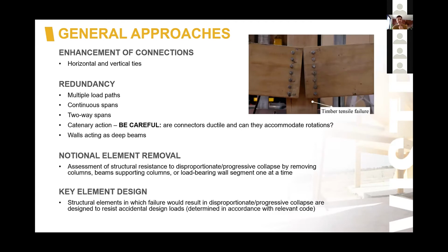And then finally, if that approach isn't adequate, you would need to implement a key element design approach. This is essentially providing overstrength to structural elements to ensure that they don't fail, and therefore you don't have disproportionate or progressive collapse.